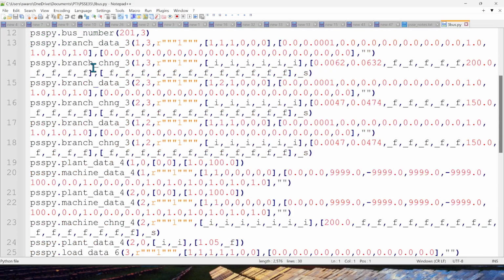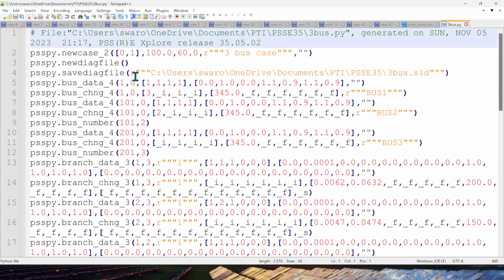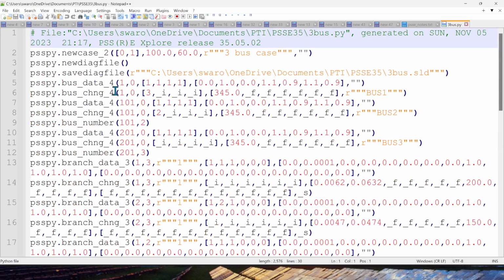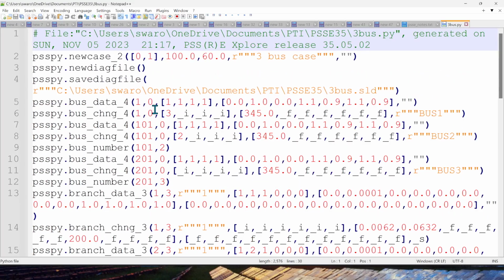It saves all the actions we have performed, and we'll show how this can be very powerful or useful to you in many situations. We will cover that in another video, but just wanted to show you the contents of this file and recommend you to always start recording your actions when you begin any new analysis or any new work as you launch PSSE, and that will do wonders for you.